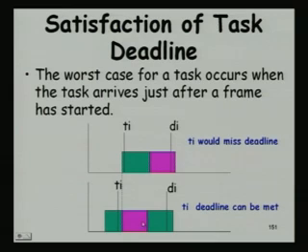Now, we have reduced the frame size, right, and the task arrived just before the frame has started, and see here there is a full frame available, we can run the task here. Here there is no frame, I mean this will be the frame which we can run, but by that time the deadline will be over. So, this is the third constraint, that the frame size can have a maximum certain size, and this constraint cannot be violated.